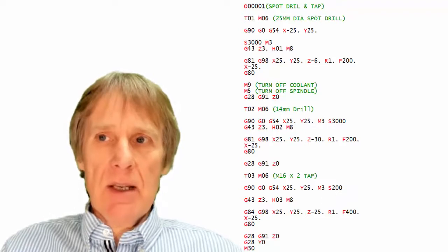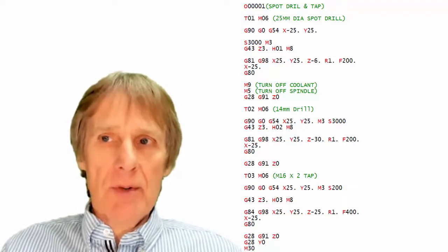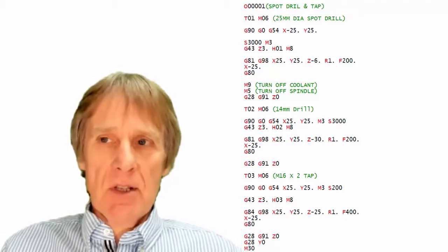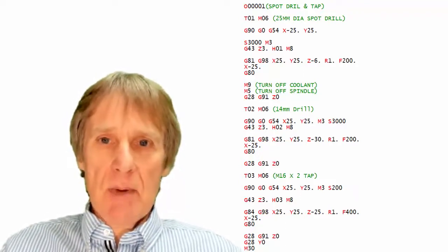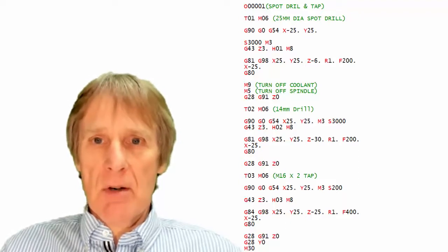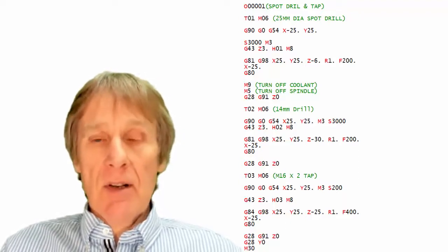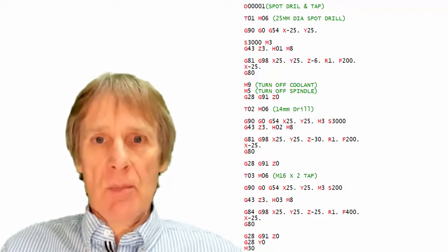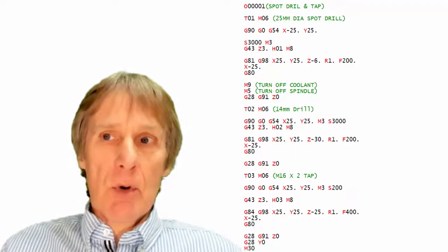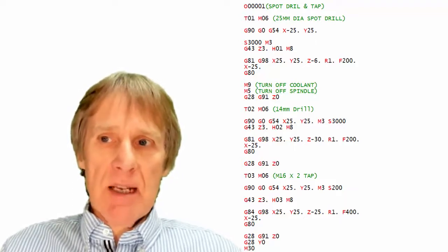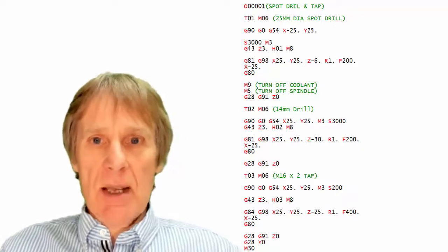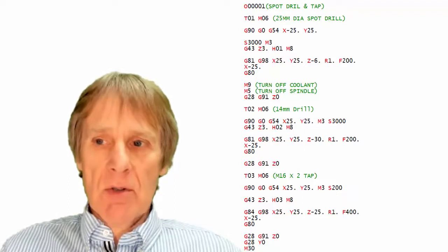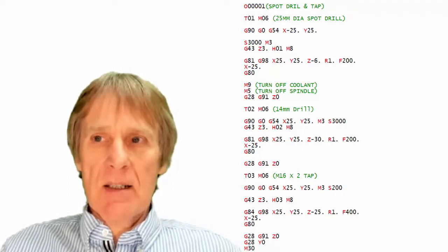And every time we hit this button, this is called program number 1. And whenever we call out program number 1, it will do this same set of commands. So this can repeat over and over again. And then if we put this part away and we don't make them for 5 years, we can come back, pick this program out and run it all again. The only thing that we have to do each time is set the tools up. The program won't change. So we have to set up all the tools ready to use, and we have to set up what we call a datum. In other words, we have to tell it where the part is on the table, which again we'll be talking about a bit further on in the course. So that is effectively what a CNC program is.